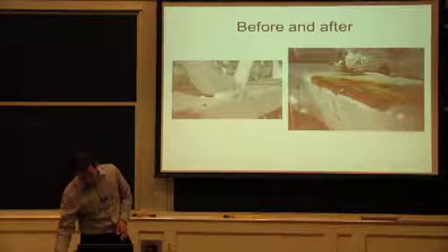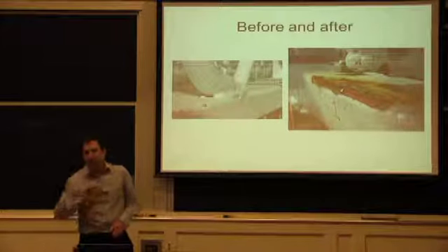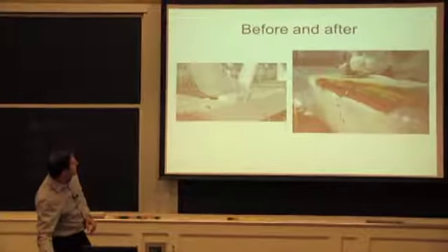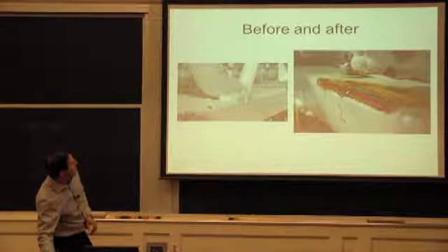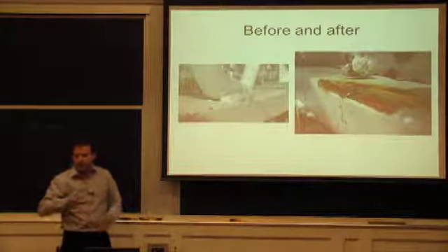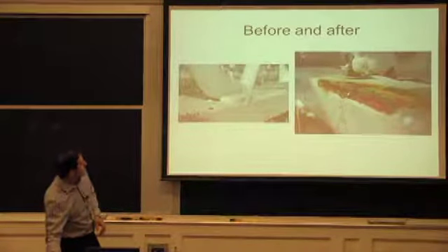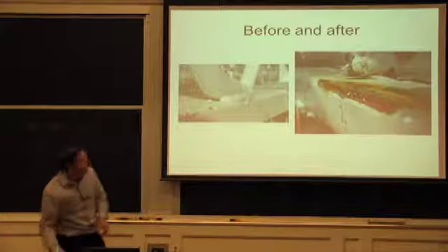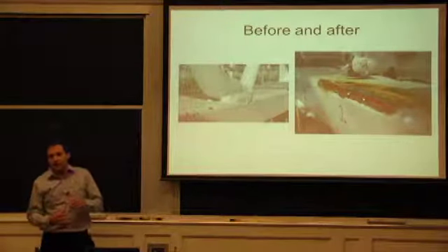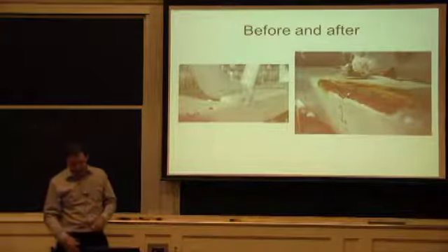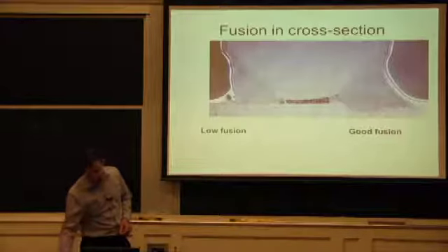Same story where you look at this weld, and we talked a little bit about convexity. So maybe today, if you go somewhere and you see this, you'd be able to say, oh, this looks like it's a little sort of deposited on the surface as opposed to being really weld fused. It has a low contact angle here, and this is the same type of weld that, after the fact, you can see just pull off from the surface of that chord, that structure, as opposed to ripping the metal apart with it.